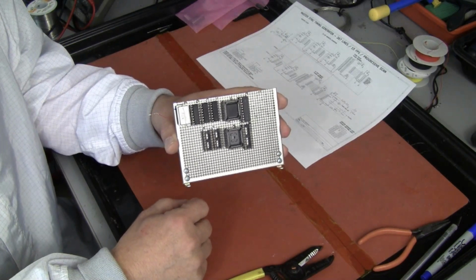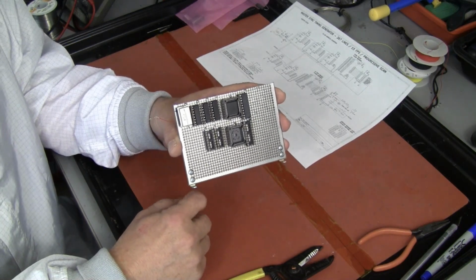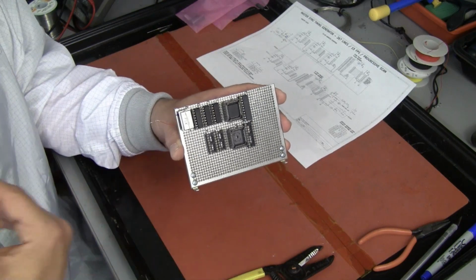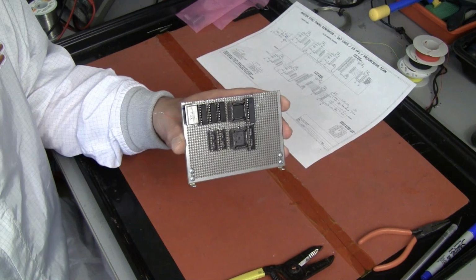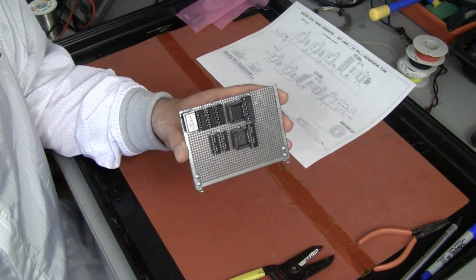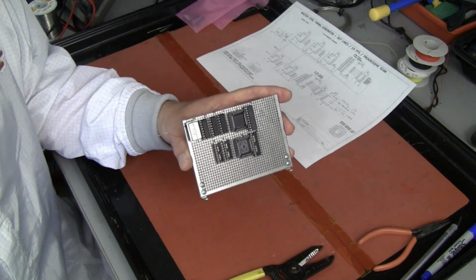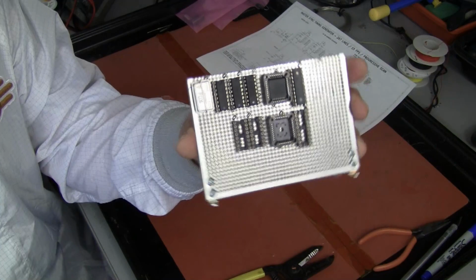Composite blanking is also complete. Composite sync is a little more complex, and as I mentioned, the vertical sync pulse is in the wrong phase, but it can be trimmed to anywhere I want it with a resolution of 256 nanoseconds. This is incredibly accurate pulse positioning. It's just a matter of changing some parameters in the program and rerunning it.